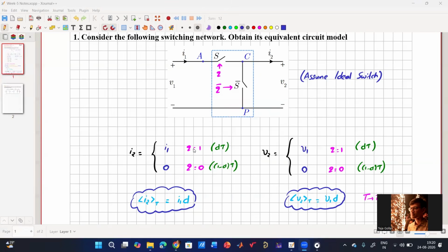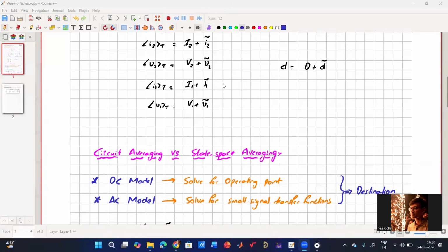But the system is nonlinear. So what we are trying to do using these methods is linearize the given nonlinear system. So how are we linearizing it? We are considering an average. First, we are averaging out all the variables, so the ripple information is lost. Now we are considering only the DC value, and then on top of that we are exciting it.